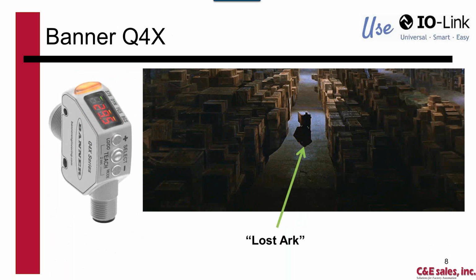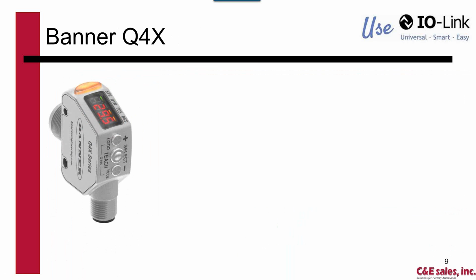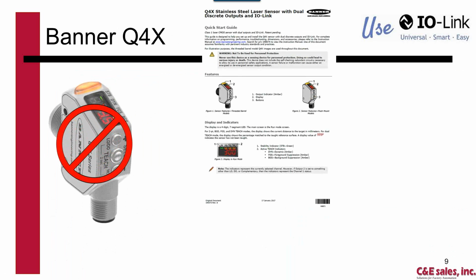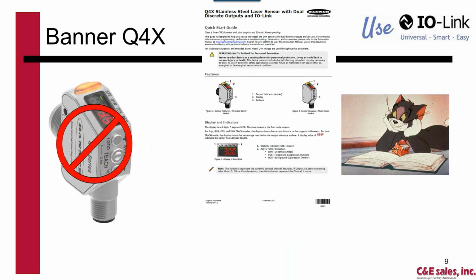Sensor technology has improved, including the robustness of the sensor, and they last longer. However, sensors do get damaged. If a teachable sensor gets damaged, then you would have to reteach the replacement sensor. Unless you teach sensors every day, you will need to find the data sheet for that sensor and then reread the data sheet in order to teach the replacement sensor.